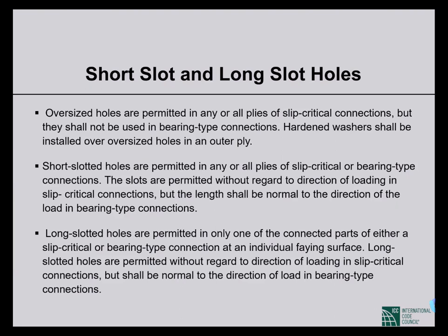Short slotted holes are permitted in any or all plies of slip critical or bearing type connections. We can use short slotted holes. The slots are permitted without regard to direction of loading in slip critical connections. In slip critical connections, we can place the elongated side in any direction. But for bearing type connections, the length shall be normal to the direction of the loading.